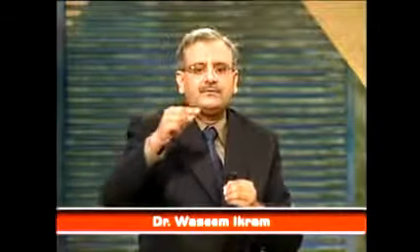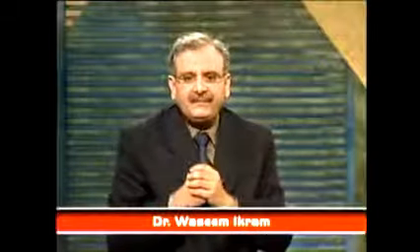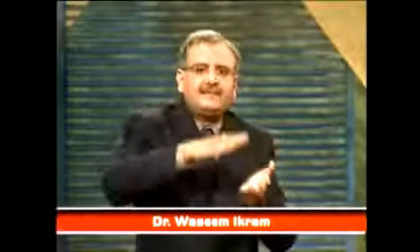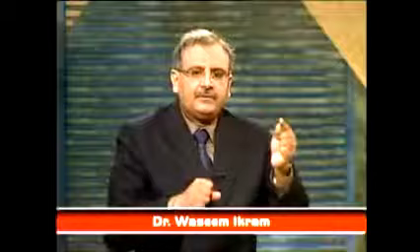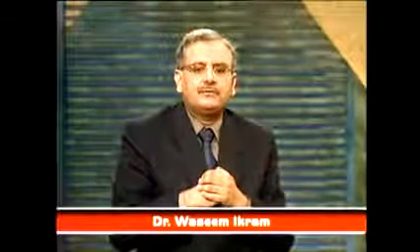So how do you represent decimal digit 0? Bits 0, 0, 0, 0. How would you represent the highest decimal number 9? Binary number 1, 0, 0, 1. Now, you can get more combinations if you use 4-bit binary. So you can also have a number 1, 1, 0, 0, which is in fact 12. But you do not use binary codes higher than 1, 0, 0, 1. So the BCD representation only uses the first 10 binary codes starting from 0000 up to 1001.